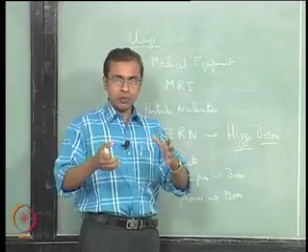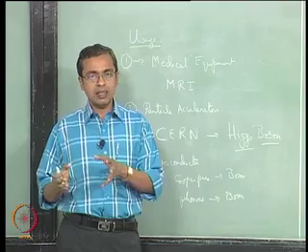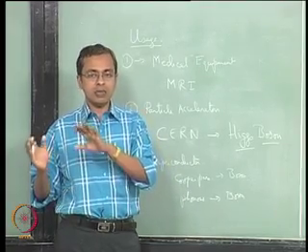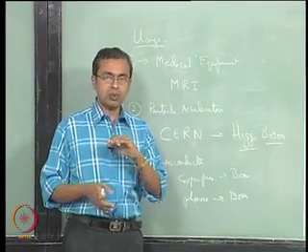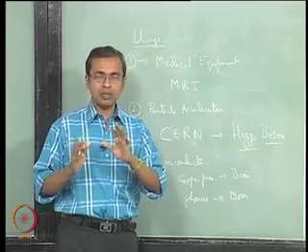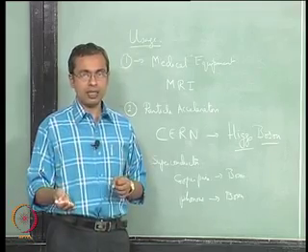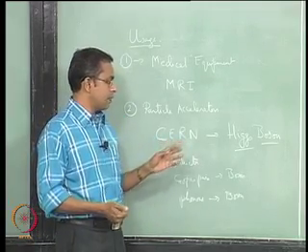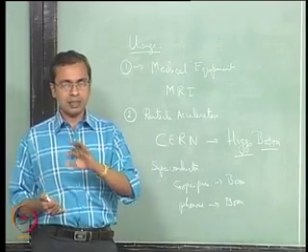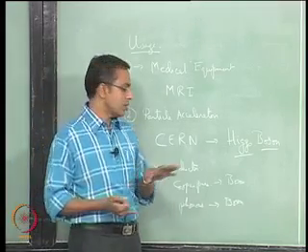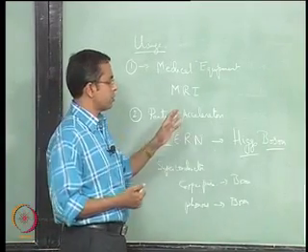It may take several weeks to very gradually raise the temperature of the affected system to room temperature so that you can attend to it, and then very gradually lower the temperature again. Reaching the temperature and coming back to room temperature has to be a very gradual process, otherwise you will create a thermal shock. So this has to be done very carefully. In addition to the fact that it is at low temperature, simply reaching and maintaining that temperature has to be done in a very controlled way. So even in that sense, there is a technological challenge in working with superconducting materials.